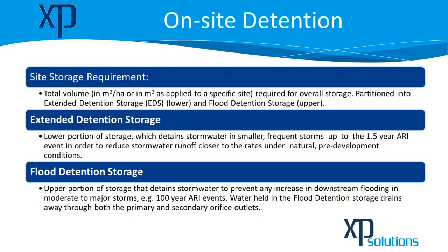So we've run through these options on the interface for extended detention storage and flood detention storage, but I didn't mention that the site storage requirement should represent the total volume. So this is for the overall storage, which would then be partitioned into the extended detention storage being the lower part and the flood detention storage being the upper part of the storage there.